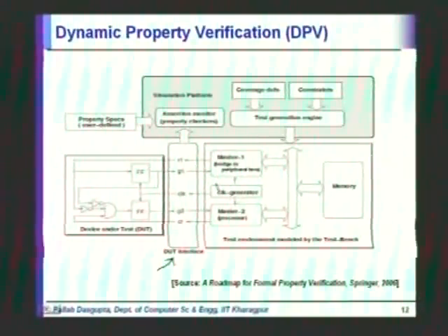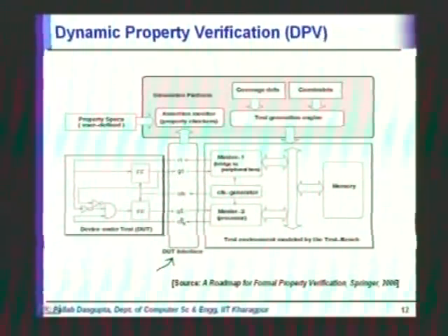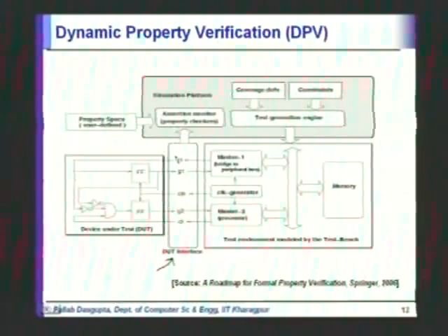Okay. How does that help? The assertions can be coded using these variable names. Right. So regardless what are the variable names used in the DUT and in the test bench, you can write the assertions using this, and then binding is actually attaching the names together.